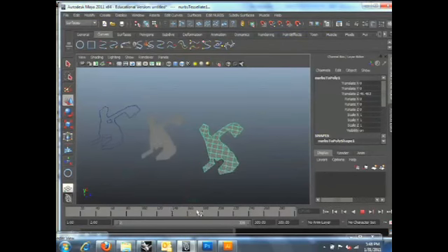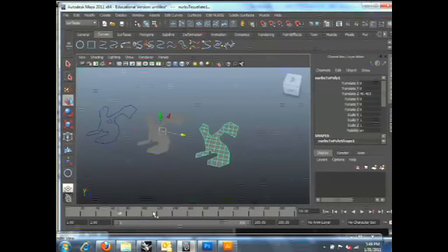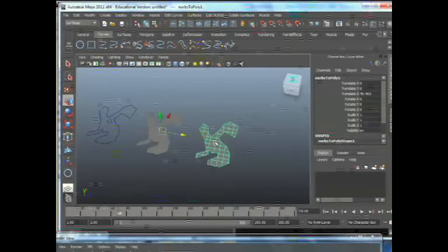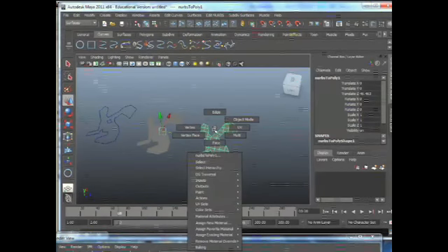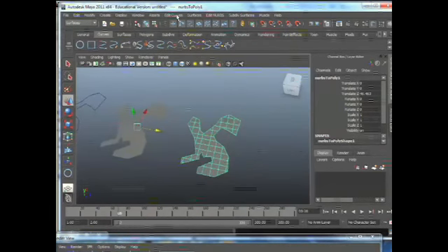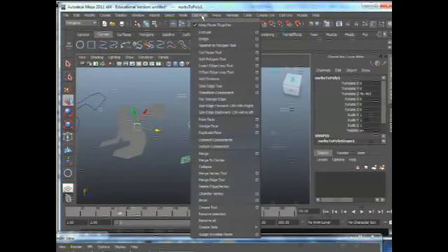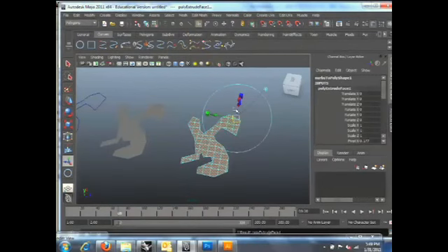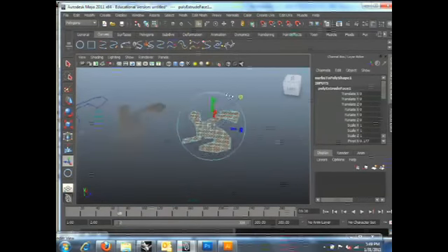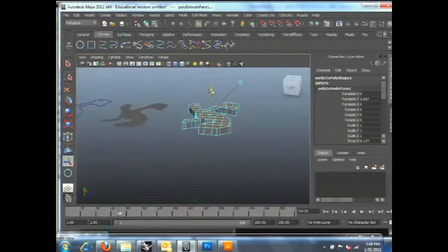If I play, you can see they all work, right? So this is the original line. This is the planar surface. This is the polygon, I can see this is a polygon face. Then the next thing I'm going to do is extrude that polygon in 3D. Just make sure the coordination is up.